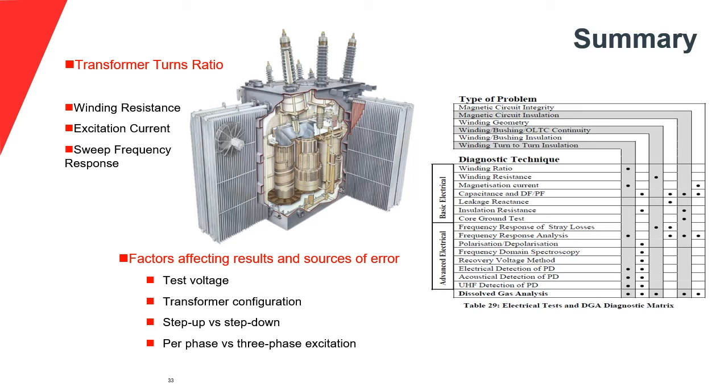So again, we need to make sure that we are not inducing a dangerously high voltage on the high voltage side of the transformer under test, and also that the unit that we are using can handle that voltage, most importantly in a safe manner, in a safe condition.